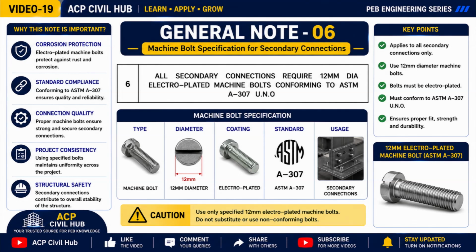Never replace these specified bolts with different grades or diameters unless the engineer's drawings specifically allow it. Following this simple requirement ensures every secondary connection performs exactly as intended throughout the service life of the building.